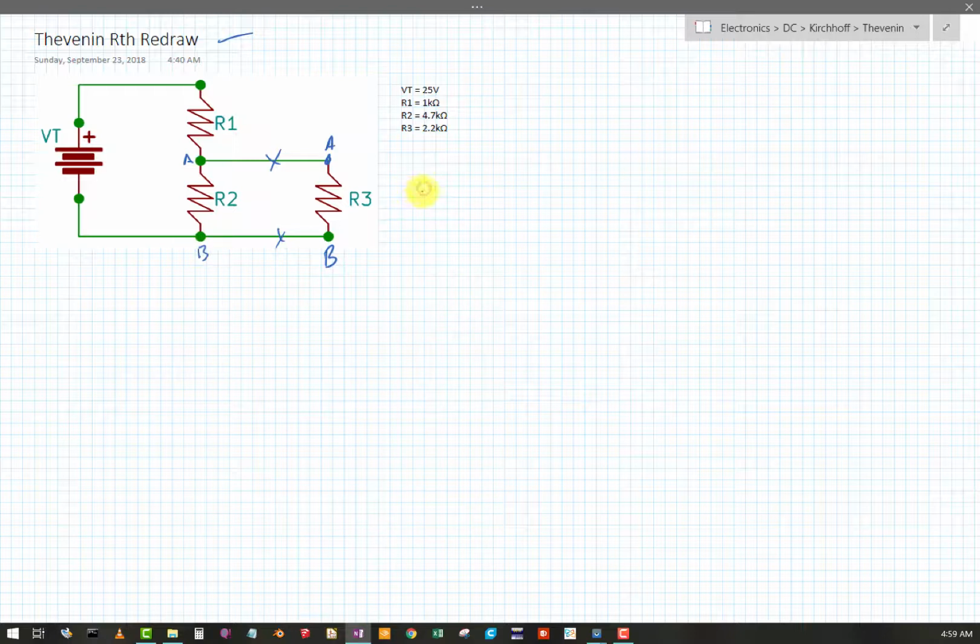So it's as if I'm taking my ohm meter and measuring those points with R3 removed from the circuit. Normally we wouldn't take a resistance measurement with the power supply connected, but the path through the power supply when the circuit's operating turns out to be important to the equivalent resistance that the load would see. So the way we deal with that in Thevenin's analysis is we short out that supply. That supply is now just a path to ground.